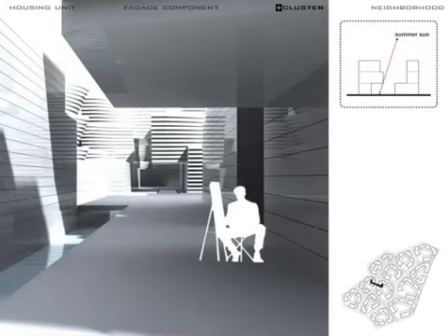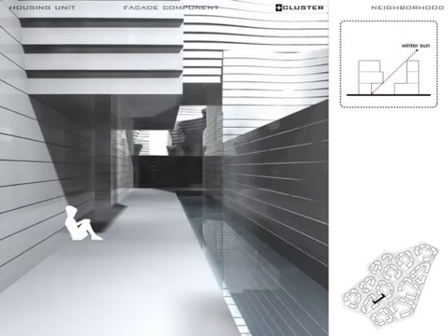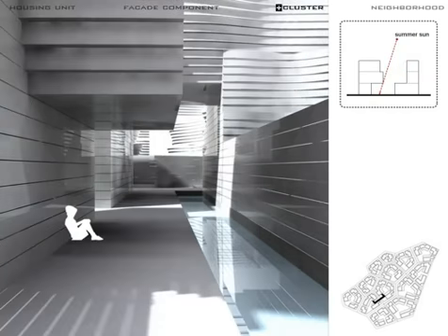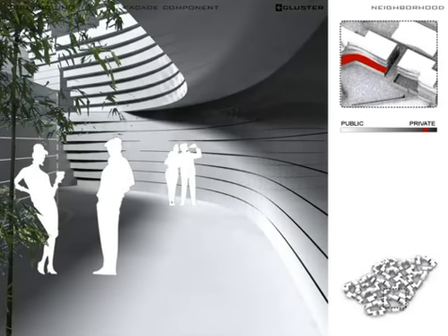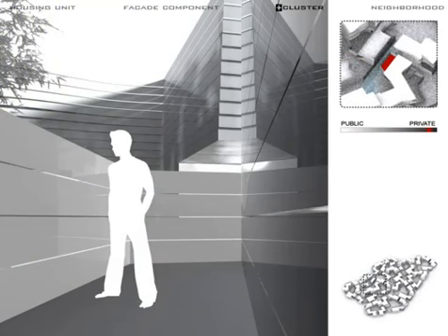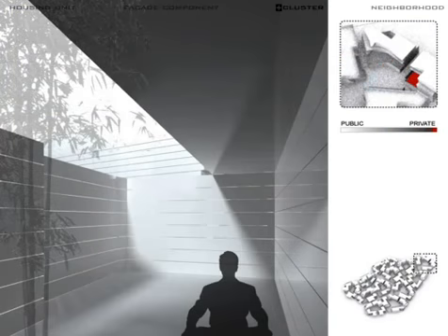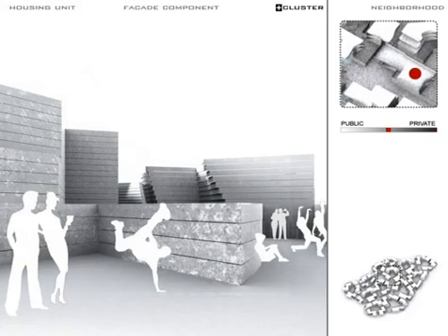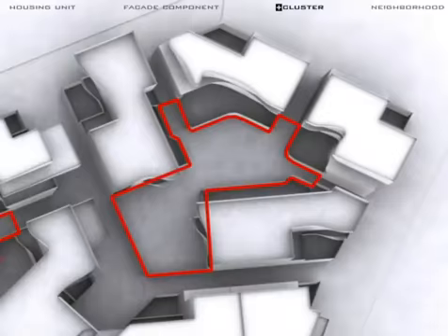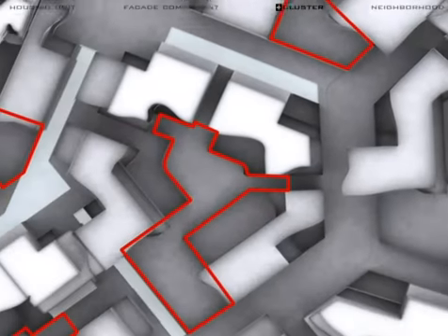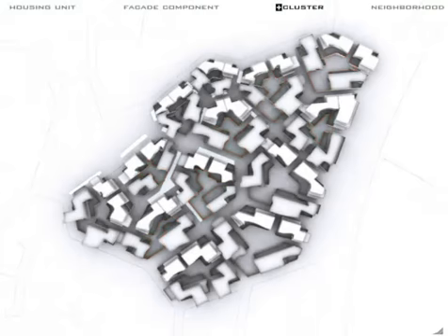The cantilevers of the units generate comfortable spaces which are exposed to the sun in winter but provide shading below in summer. This feature is particularly favorable in Shanghai's humid weather. These spaces below allow outdoor activities to happen in the rainy season. A series of courtyards with different degrees of intimacy are created and therefore offer various spaces for different people and activities. Some upper courtyards can be shared by different families and therefore change the configuration of the relationship between families in different plots. The collective courtyards vary in size and configuration, and can accommodate different outdoor programs.